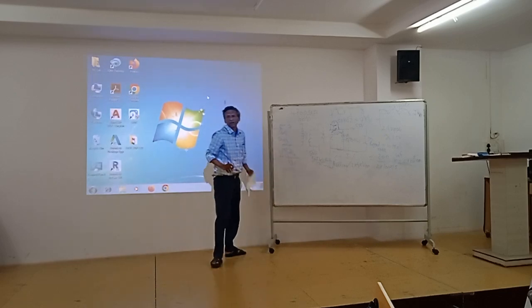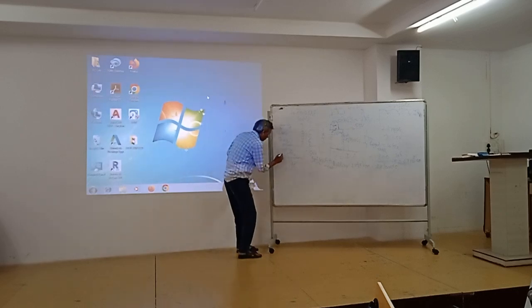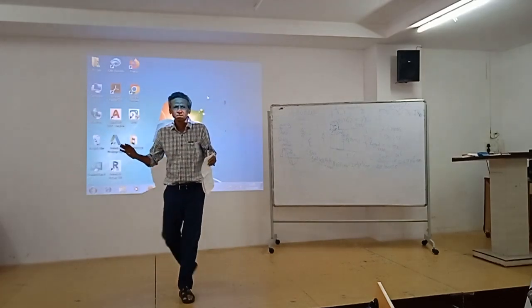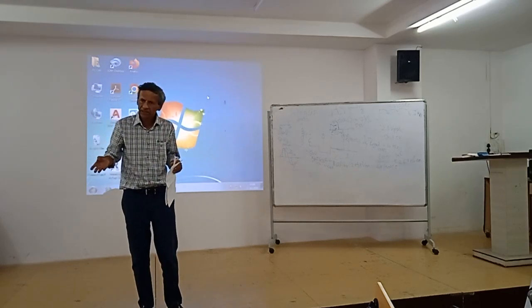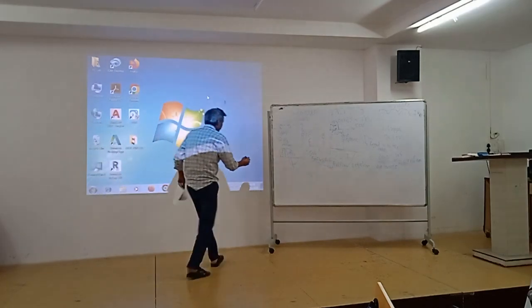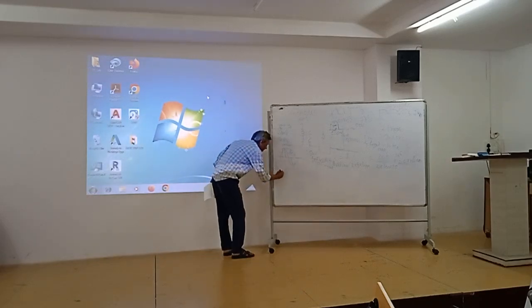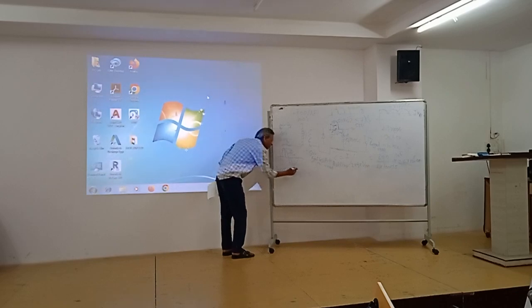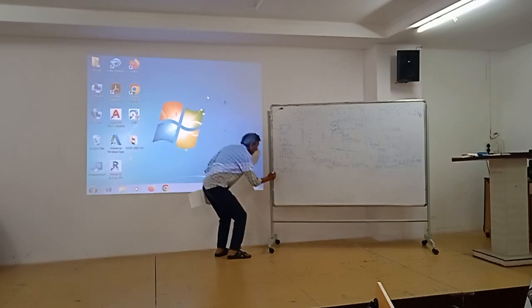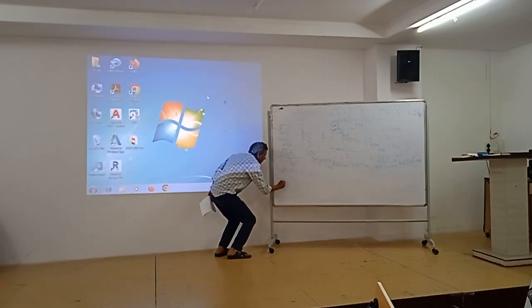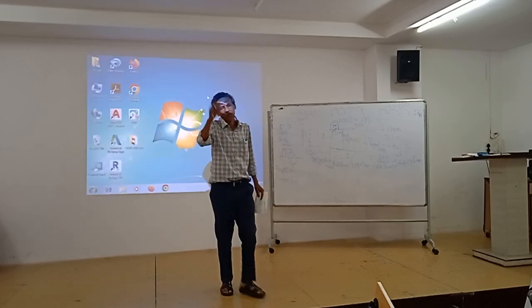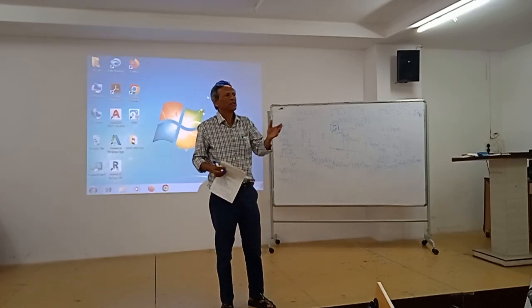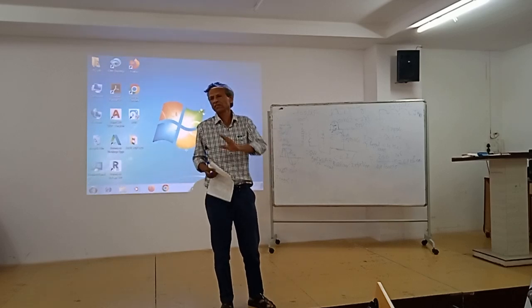So the first thing is clear that this is drawing non-sinusoidal current. The moment it draws non-sinusoidal current, it generates a lot of harmonics, current harmonics. And current THD will be around 60% roughly, while the statutory limits say that ITHD cumulative should be less than 5%. This is the instantaneous value, but then you accumulate it, and there is something called TDD, total demand distortion, which should be less than 5%.